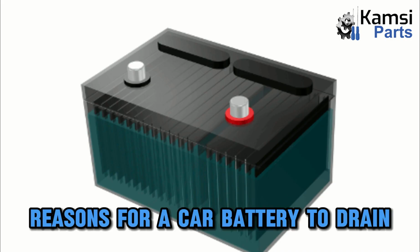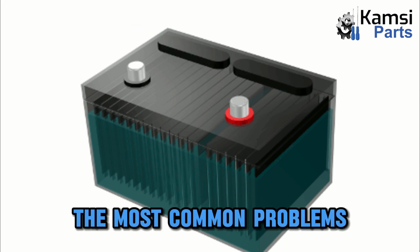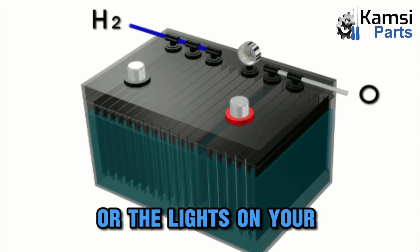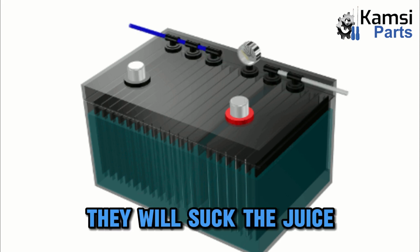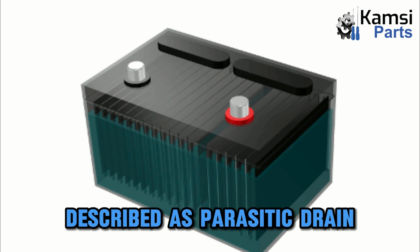Reasons for a car battery to drain. There could be more than one reason for a car battery to drain. The most common problems, however, are: 1. Parasitic drain. If the electrical devices in your car or the lights on your car are left running even when your ignition is off, they will suck the juice out of your battery slowly but dramatically. This is often described as parasitic drain.